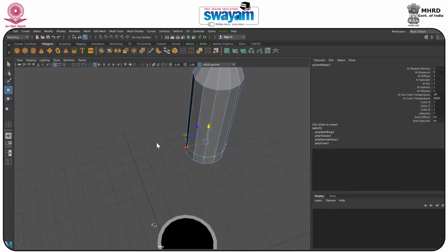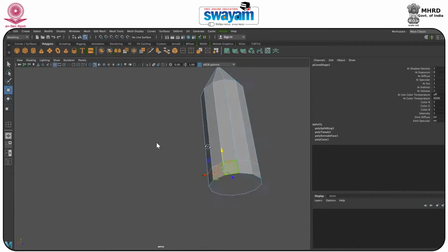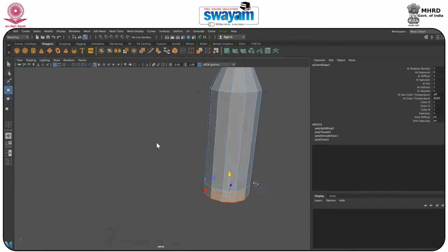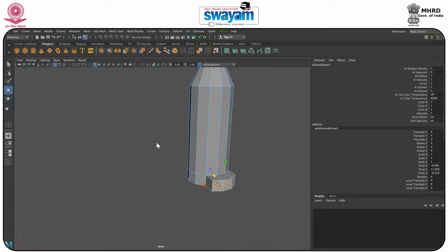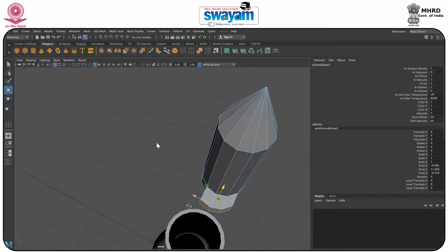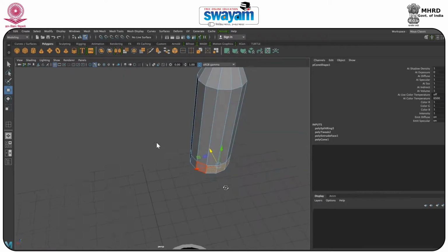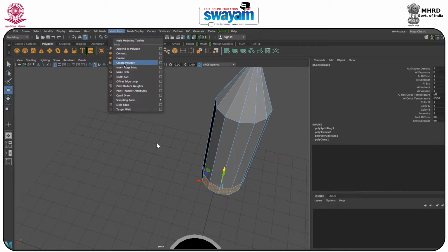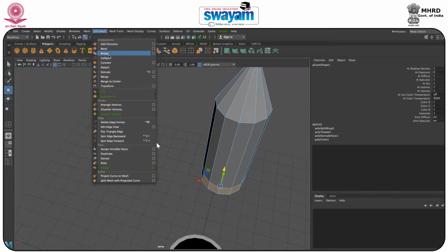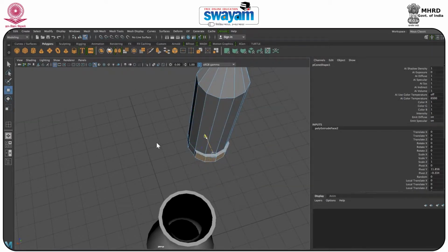And now the main thing happens is that I will just select the two faces. 3, okay, 3 would be fine, and after that we'll go to edit mesh, extrude the same in the outward direction, and after extrude, Control Z, we'll select 4 of them. I think 4 would be fine. Now it's selecting the whole loop, so we'll go to extrude, and after that we'll just move it outward.